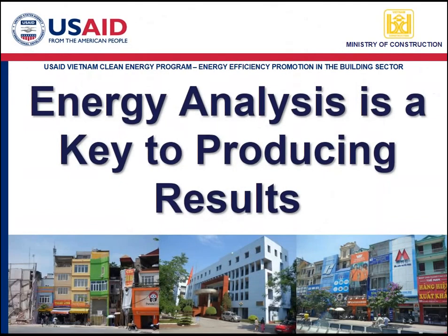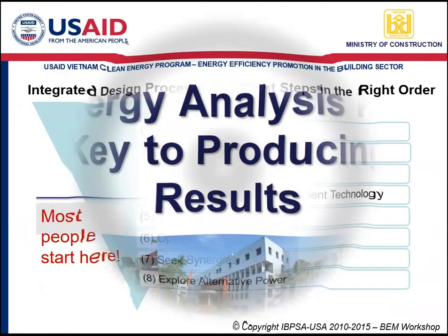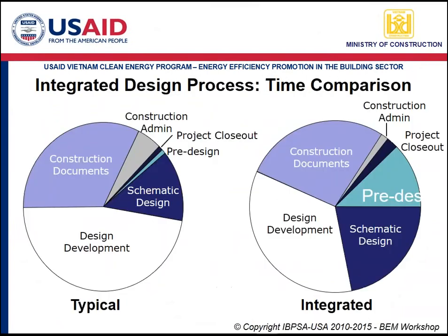Okay, an energy analysis, what we're learning to do today and tomorrow, is a key part of the integrated design process. You use energy analysis very early. You use energy analysis even in pre-design and in early schematic design to make decisions.